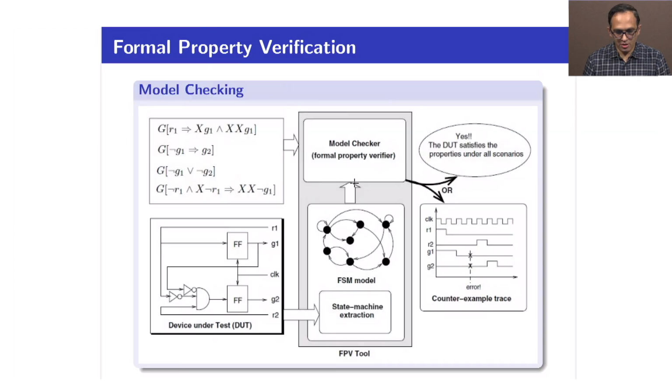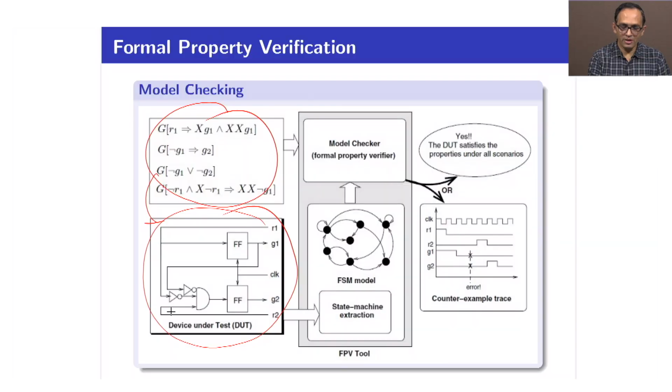To give you more emphasis here, think about I have some implementation. Now, to check this property on this implementation, you cannot just check directly on this kind of implementation. What you have to do? You have to identify the finite state machine that is happening inside. So, you will effectively identify some finite state machine like this, and this is basically FSM state extraction. We will talk about that more.